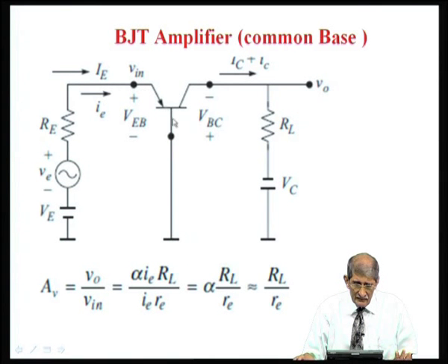I have the DC which biases in the forward bias direction, and I have a superimposed AC signal which drives a current I E through that, and that is the input voltage V in that comes across this point, between the emitter and the ground. That signal is whatever current comes through that into the resistance seen here. The resistance seen is for the AC quantity, the incremental quantity. So, for the signal, we will see how much is the resistance here.